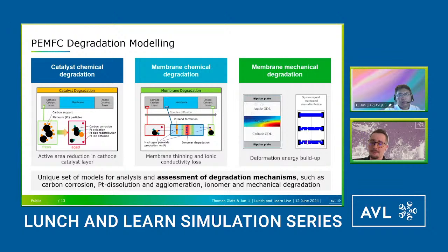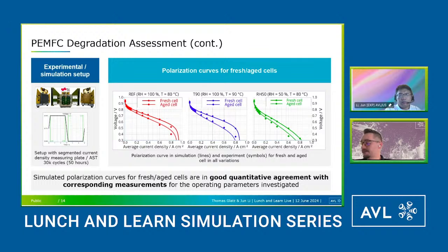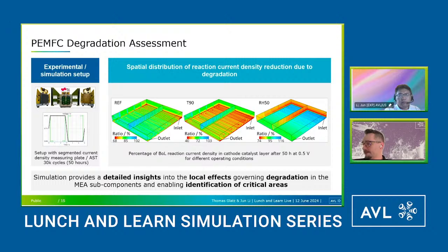And yeah, this is probably a topic by its own. So we might do another lunch and learn on just the degradation topics moving forward. Also, meanwhile, we have quite good validation data for the degradation, both with universities, as we've seen it here, but also with industry partners. Here's the slide that shows it in 3D CFD. So really the localized data makes quite an impact on the degradation. So 3D can really help you design this stack and the cooling plates nicely.